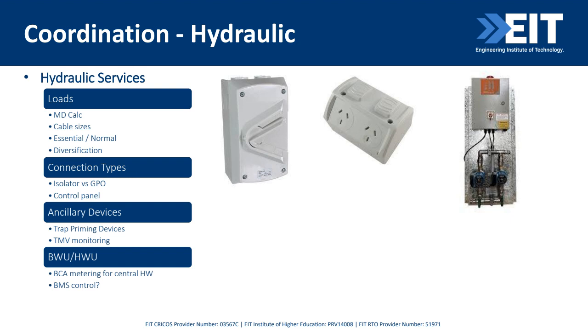Okay, hydraulic. So hydraulic services cover your cold water, your hot water. Sometimes they also cover gas. So this is very similar to mechanical. So the things that we've already spoken about is your load. What equipment, where's it going? Single phase, three phase. Do you want an isolator or do you need a power point? How does your equipment connect to a power system? Or do you have a control panel, so you just need a cable? So they will tell us their equipment and the load, we will tell them the fault level, and we will provide a power supply.